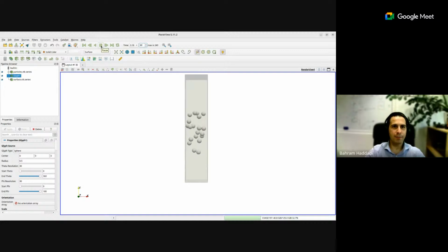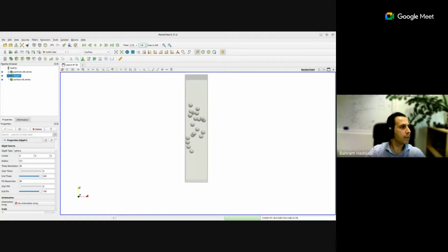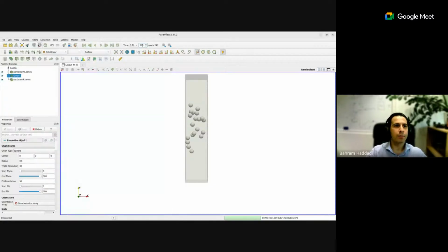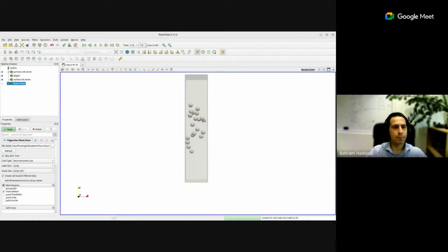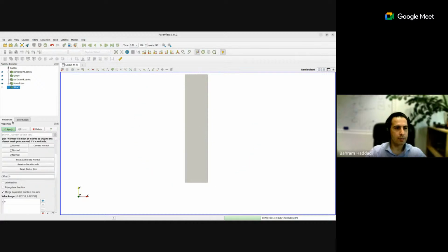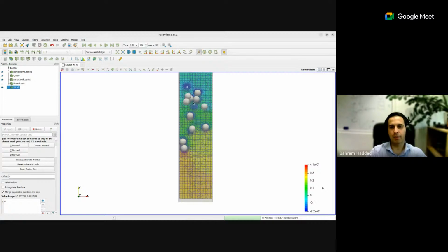But let's load also the CFD field side by side because it gets quite interesting if we can see that one also. As Hamid suggested and recommended, let's use the foam.foam file. Oh, we need to go for the decomposed case. And then let's create a slice in the middle. So that's the Y normal, yeah, no, Z normal, sorry. Don't show plane, don't triangulate it, and apply. Good. And so that's what I wanted to show.